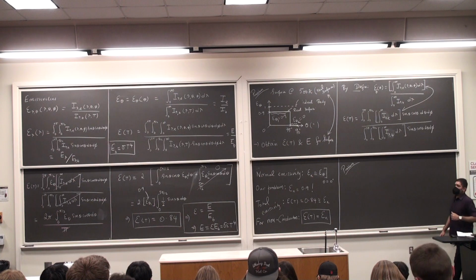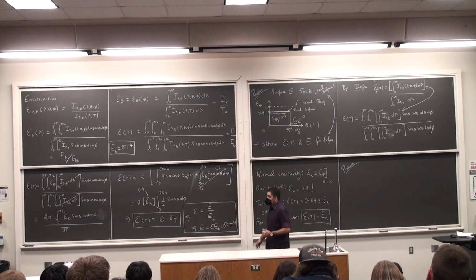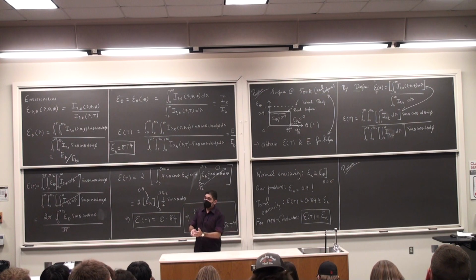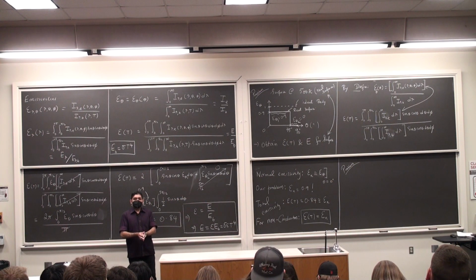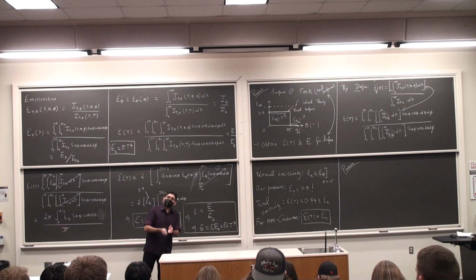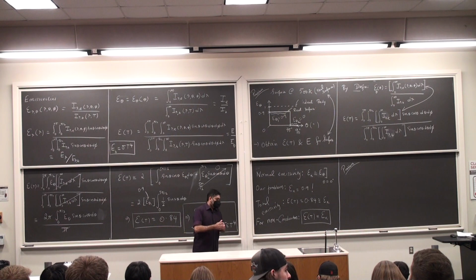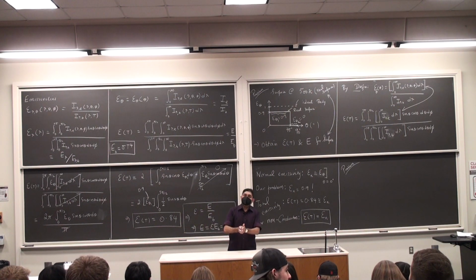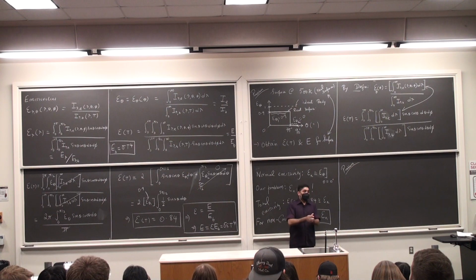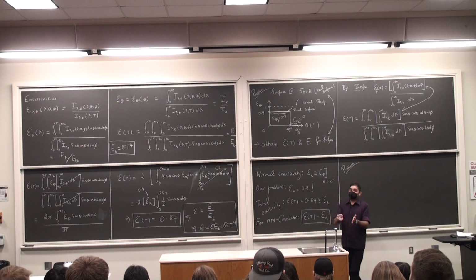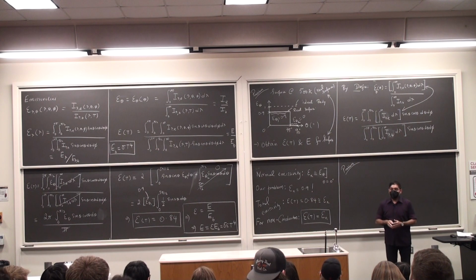Okay, so the next problem is on absorptivity. We did emissivity, and we are now looking at absorptivity. If you combine them together, you get total radiative flux, which is what we really want. We still have one last giant leap to make, which is Kirchhoff's law of radiation, which will in fact tell us when epsilon is equal to alpha. You remember alpha was absorptivity. We will eventually come to the conclusion that for certain surfaces, all of this that we've done is a waste of time. Epsilon is equal to alpha, you just move on.